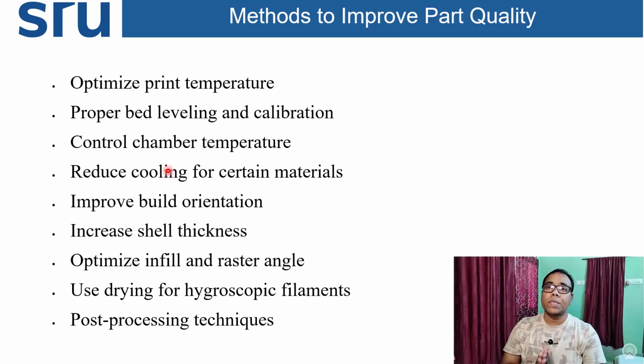Part quality always means your print quality in the X direction, Y direction, and Z direction should be uniform, and optimal temperature is required, so that there is uniform adhesion of the extruded material with the build platform, and layer upon layer bonding should also be perfect.